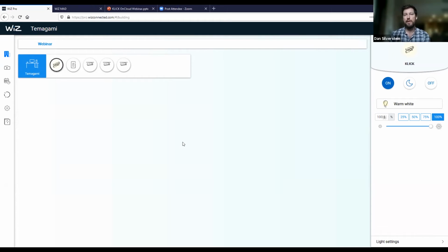The other advantage is that you have one room controller for multiple segments. If we were going to go with one driver per area, one dimmer per area, each segment would have an individual dimmer on the wall. So if you wanted 5 controllable segments, you'd end up with 5 dimmers on the wall. From an interior design perspective, we're trying to move away from those banks of 6 gang switches that nobody knows how to use. So now we get one device on the wall. It's a room controller that controls the entire space, and it lowers your total overall cost of installation.